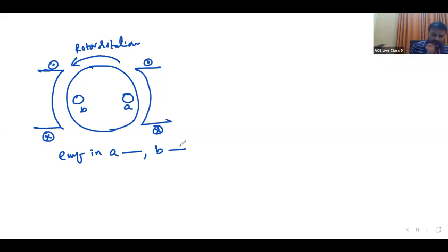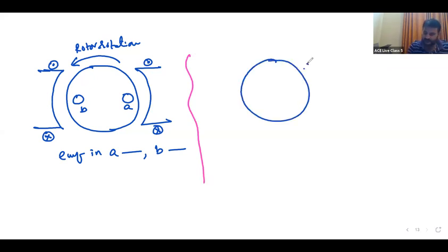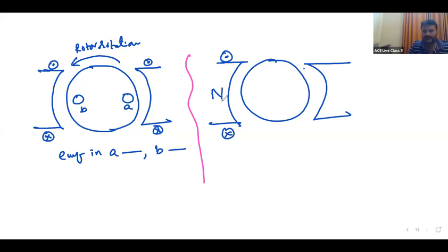Yeah. So for this, what is going to happen? Flux direction, you need to find from the poles. Poles are found by the thumb rule, na? Current is entering, current is leaving. For this question, this is cross, this is dot. Which pole does it act as? North pole, na? Current entering, leaving, north pole. And this is cross dot. It acts as a south pole. These are the conductors.